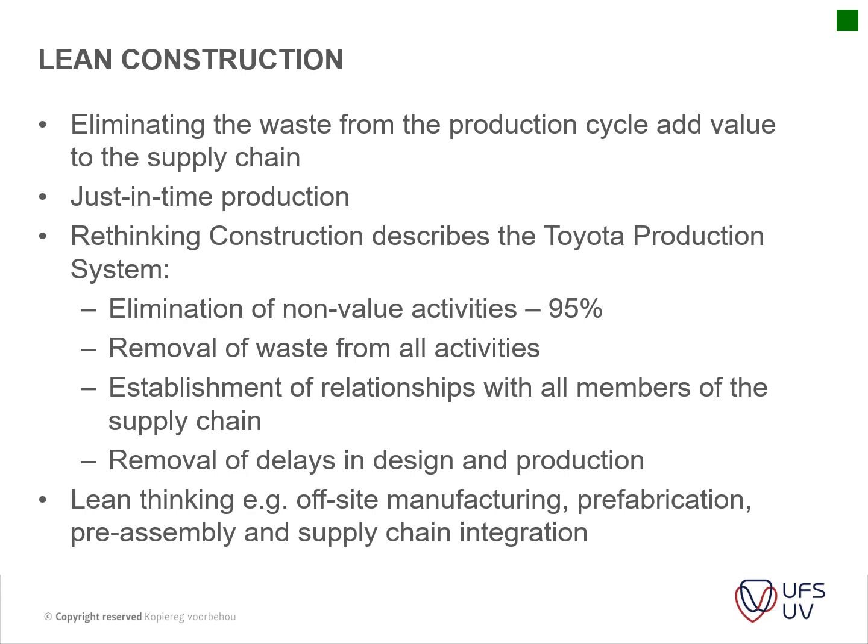Lean construction is a concept developed from the Toyota production system, and we're going to look at that. It's mainly focused on eliminating waste from the production cycle, and it adds value to the supply chain. It's a matter of just-in-time production, not having too much material on site. It's usually delivered a day or two before it's actually installed, and thus you do not need a big site to store all the material.